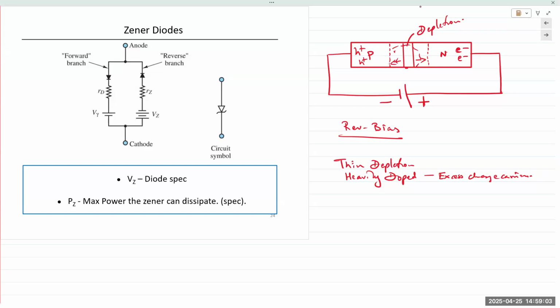And this process is known as avalanche, because every electron that is now a free charge carrier will collide with another atom and will result in another electron coming free. That electron might collide with a few other atoms, which causes a few more electrons to come free. And so there's a cascading effect of free charge carriers being generated. The longer you apply the electric field, or the higher the electric field you apply, more and more charge carriers are generated. Eventually, the device will completely shut down because you have now exceeded the power capability of that device. It will blow apart.